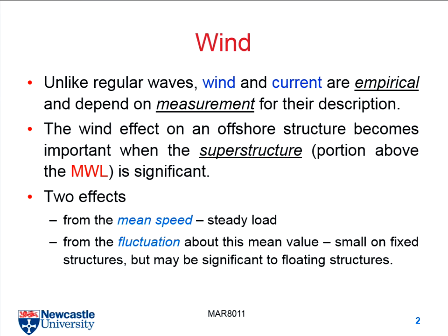The second one, of course, even if I don't say that, you know, if we have a project, here is the water surface, here is the part over the water surface, and here is the part underwater. The wind force is not very important for this project, because you have a big current force underwater, and the force from wind probably is nearly zero compared to this one, or to waves.